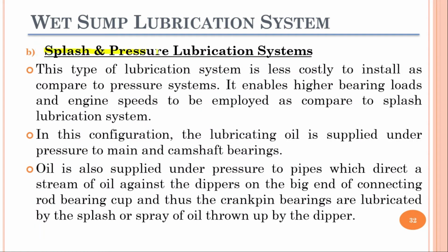Moving forward, we have the second type of wet sump lubrication, and that is the splash and pressure type lubrication system. These lubrication systems are more effective than the splash type lubrication system, and they are less costly as compared to the pressure feed lubrication system. Similarly, they can enable higher bearing loads, and higher engine speeds can be employed as compared to the splash lubrication system.